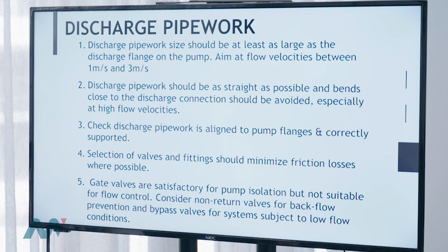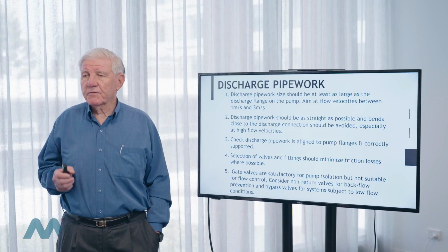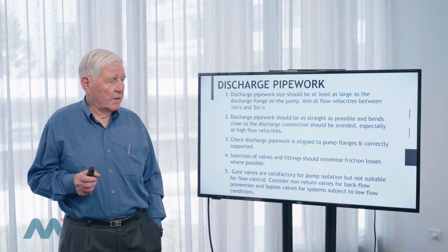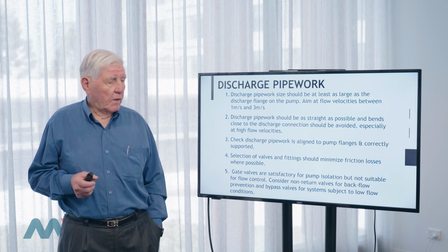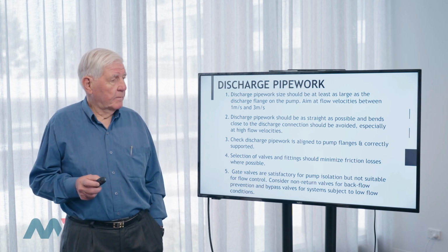And finally, gate valves are often used in pump installations. These should not be used to control flow. They are there for isolation purposes only. And you should consider non-return valves to avoid backflow in the system.